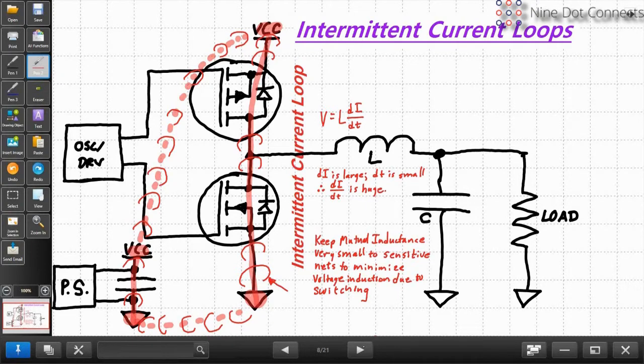Another common thing that needs to be understood. These devices are switching, and there is current flowing in the inductor. Now, ideally, you'll turn one off and turn the other on at exactly the same time. And when you do that, the current will change from going through one device to going through the other device. Now, it doesn't just invent itself in the middle of thin air. It has to come from somewhere. So if it's drawing it up from ground, that's great. But suddenly, when you start drawing it down from VCC, where does that come from? Well, it actually is pulling it out of a capacitor that is tied between VCC and ground somewhere. And hopefully that capacitor is fairly close to the MOSFETs, so that current doesn't have to go a long distance down bus bar paths to actually get there.